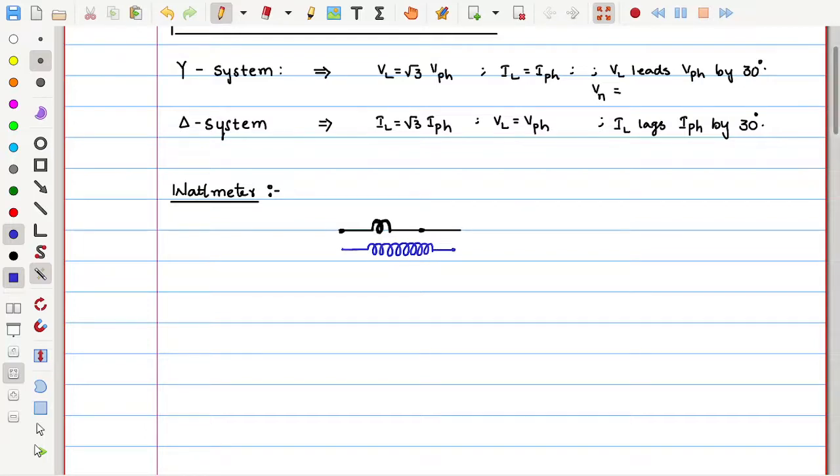These are the two important elements in a wattmeter. One is the coil made of thick wire with fewer turns, and one more coil made with fine wire but more turns. Remember that whichever has fewer turns contributes less impedance. Whichever has more turns contributes more impedance.